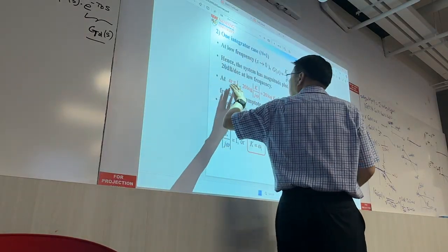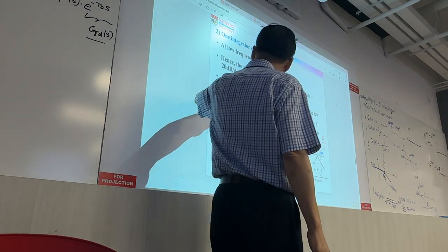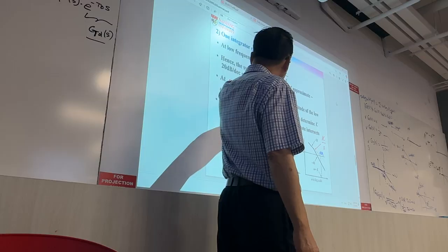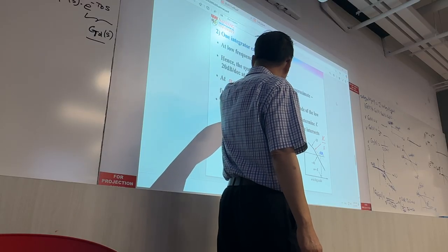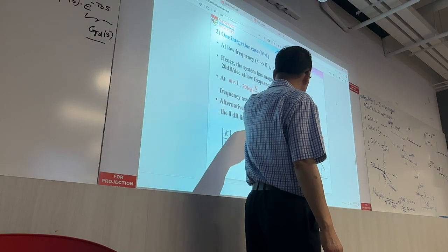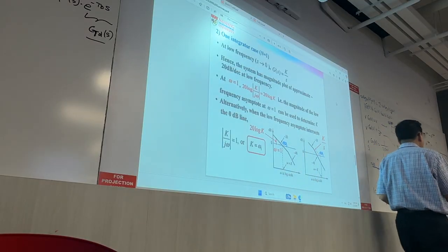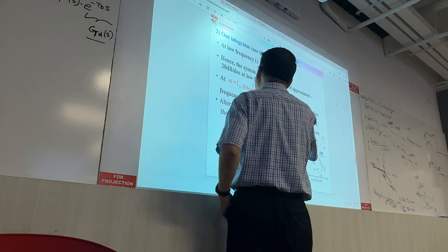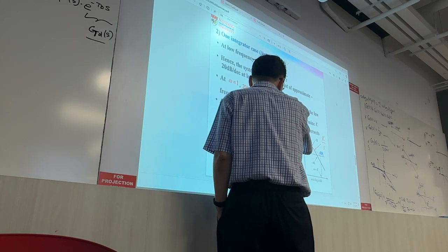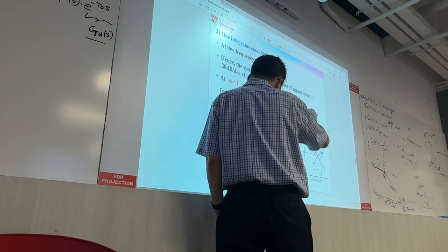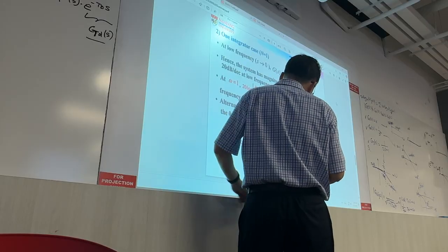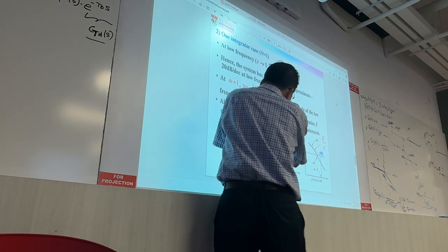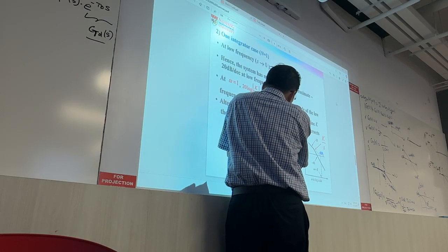And then we can see how to compute some specific points. When omega is 1, 20 log of 1 here, K is the original. So it will be equal to 20 log K. So here at frequency 1, okay. This is omega equal to 1.